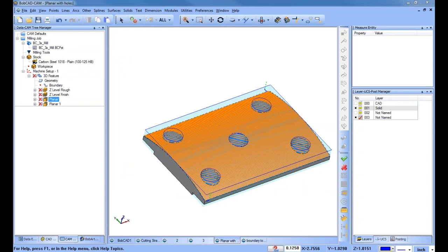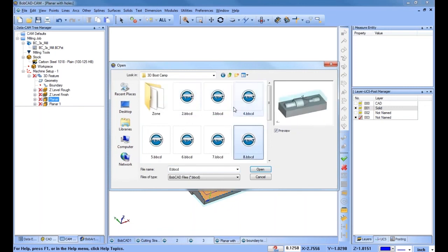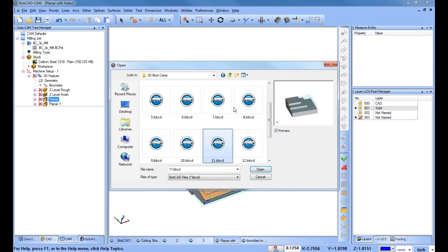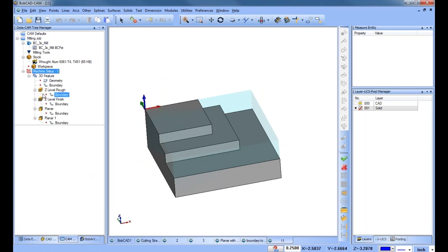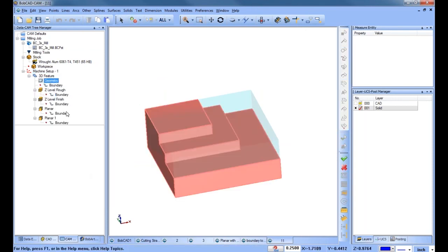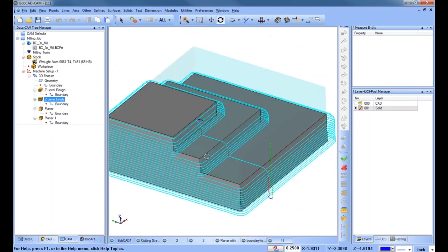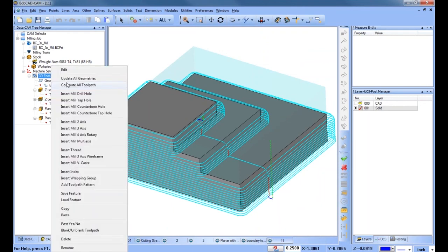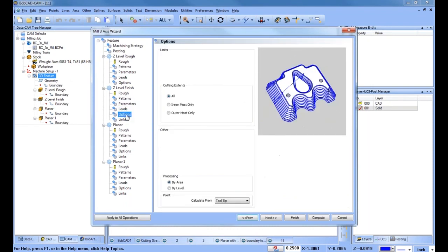Where do you set the Z-level rapid plane between moves and operations? There's a specific part that I set up for this. Let me see if I have it here. This one here. One of the things that you'll see is when you do a Z-level finish, you're going to get this direct connect. With this direct connect, the tool is following along this surface here, and that's really not the best scenario. So generally how I would approach this, there's a couple of ways to approach it.